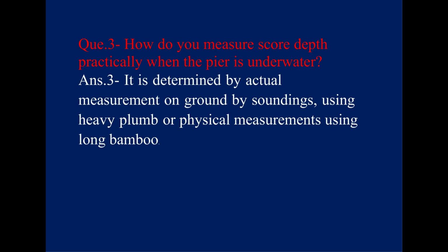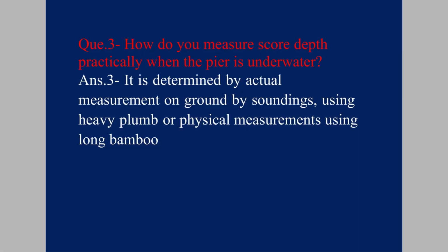Question: How do you measure scour depth practically when the pier is underwater? Answer: It is determined by actual measurement on ground by soundings, using a heavy plumb or physical measurements using long bamboo.